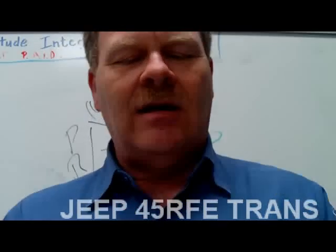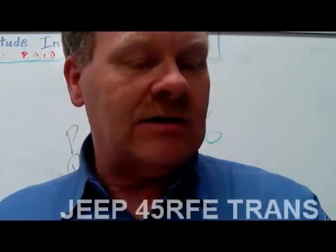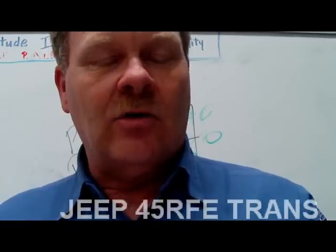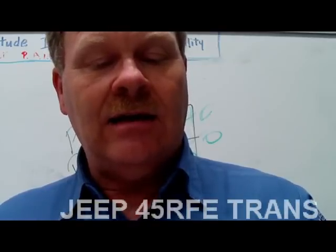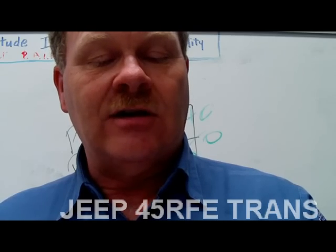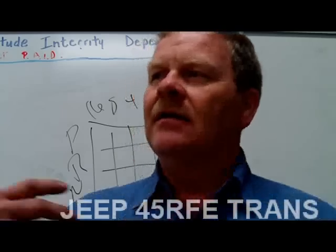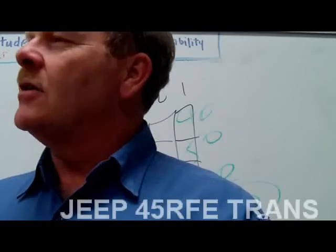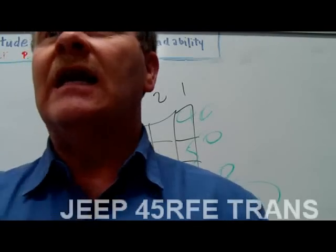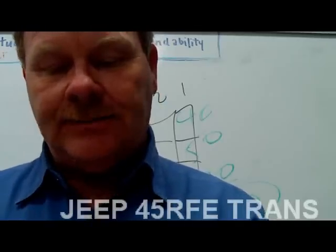All right, direct TCM outputs. Now we're talking about outputs. Inputs and outputs. It's all about computers. You got to watch this. There are questions being answered here from your test. They include the transmission control relay. That's an output, which the TCM energizes to provide power to the pressure switches and shift solenoids. You got a TCM relay that's going to power up all your switches and solenoids. That's what relays are good for. The engine controller can turn a bunch of stuff on by just making one input. Click, everything comes on. So you got a relay in your box out there for that.